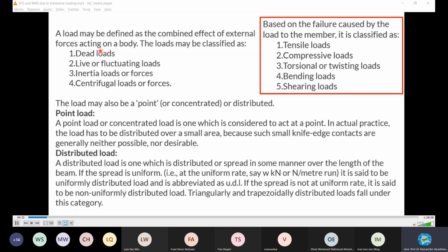So you have dead load, and live load, all the moving loads, all the objects which are in a dynamic condition, with inertia and forces. In addition to that, it will create its own responses, right? Sometimes it will form a loading to the other end or to the following members. So you need to calculate the inertia of the member before you select. And then finally, centrifugal forces, and other types of forces that are acting on it, apart from dead loads and live loads.